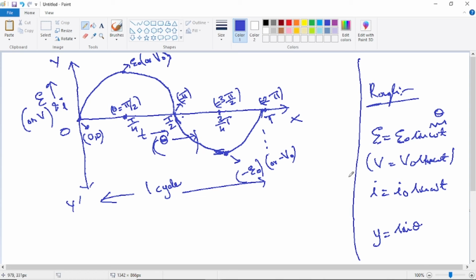The reason is, just see the equation here. I is equal to I naught sine omega t. What is I naught? We have seen that I naught obeys Ohm's law. It is nothing but peak EMF, E naught, divided by resistance. So the equation becomes like this. Now assume that the resistance is 1 ohm and EMF is say 10 volts. 10 by 1 is 10 only, so peak current also is 10 amperes.